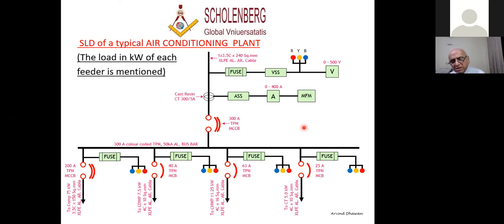Building orientation may change, requirements may change. There will be a lot of discussion between the consultant and the user. And finally, when everything is frozen, the consultant will issue the fit for construction drawing to the contractor for execution. Execution is never done based on tender drawings. So after all the discussions, the fit for construction drawing is given. It may be the same as the tender drawing, maybe slightly different, but normally changes happen because the client may have certain other views in the course of discussions and change in requirements.